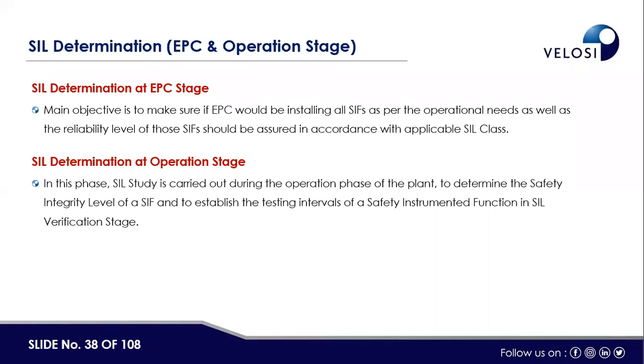Or you can also do SIL without HAZOP, but it will require a little more work from the SIL team, and there would be more guesswork rather than actual determination of hazard. There are basically severity and probabilities, which we normally use at the SIL determination stage. My colleague will be covering that in the next example.